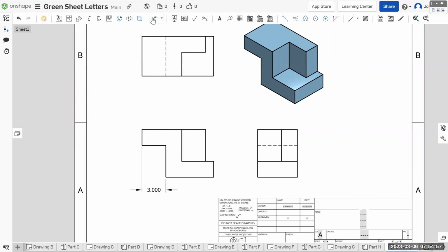Okay, dimensioning, going to the left, the next thing that happens is this edge, which is the distance to where this face starts. And this is going to a hidden line. Excuse me, it's going to a non-contour. It's an interior line, not ideal. Up here, it's the same thing, not ideal. But anywhere else, you're going to have to cross into the shape or onto the view, as I would say. So this is about as good as it's going to get.